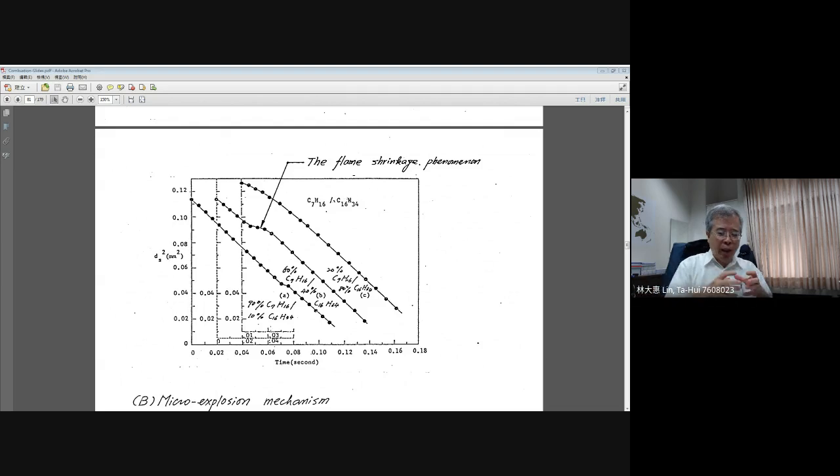In this case, the droplet does not change too much. It remains at almost a constant radius. When the droplet size does not change, this situation tells you the droplet is absorbing heat for heating. Now you can see there is a small change in droplet diameter, and they are waiting for the heating of the C16. Later on, you will find they continue to follow the linear curve, the d squared law. Okay, this is the influence coming from the 10% C16 fuel,